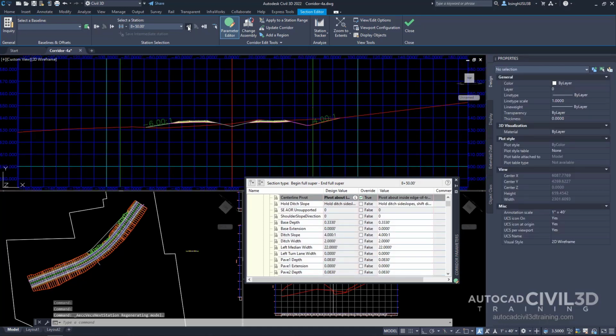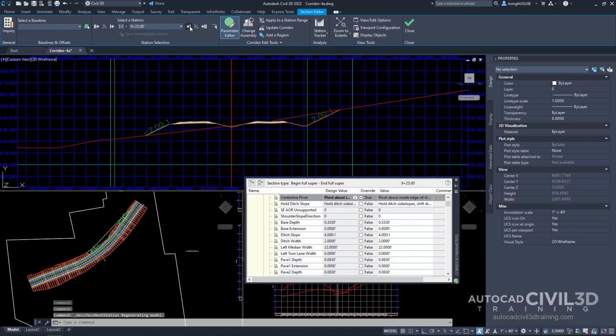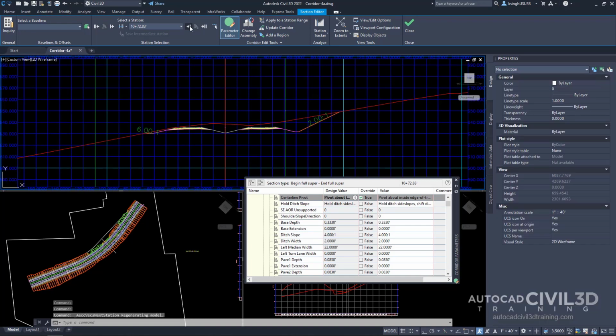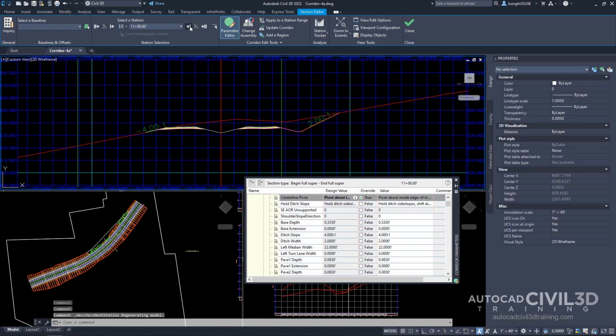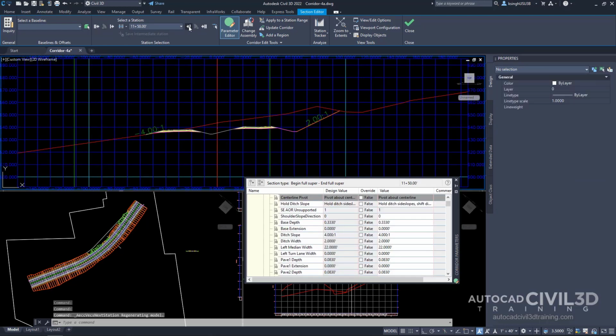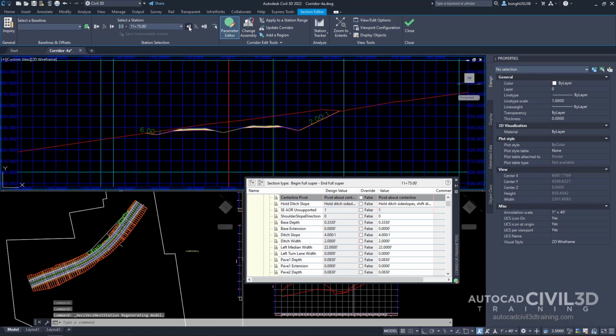And you can see how the centerline pivot override is currently checked. You can see how it's still checked off. Now we're at 11. Now if I select the next station, you'll see it uncheck. There we go. We'll go all the way to 1175, and you'll see that this override check is cleared. So that's how you go about editing corridor sections in Civil 3D.